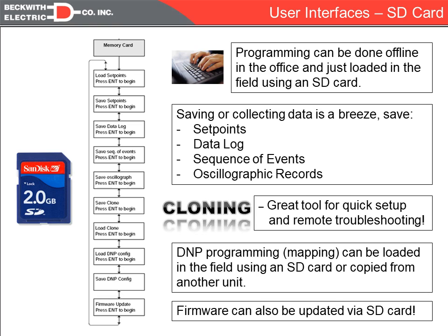Finally, we can update firmware from the SD card. When you do that, it's an automated function where it'll automatically place the control at manual. It'll copy the settings from the control onto the card, download the firmware, error check the firmware, download the settings from the card back into the control, and verify those with an E-squared checksum. And then if everything is normal, it'll automatically return the control back into automatic operation. And this process will take under a minute.